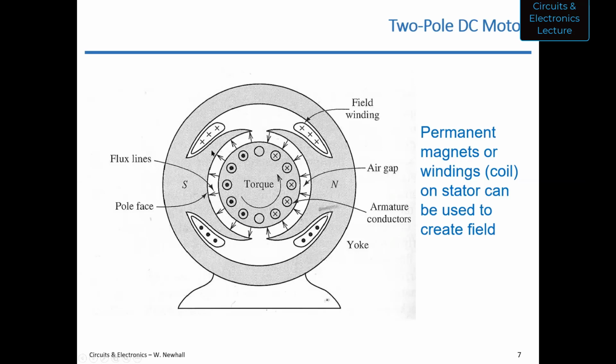So now you can imagine that magnetic field is created by those two field windings, and then you have commutator bars conducting current into one side on the right side, out of the left side here, as shown in this picture, and so you get some torque, and this motor spins. So that is the principle behind how you make motors work with either permanent magnets or electromagnets creating the magnetic field.